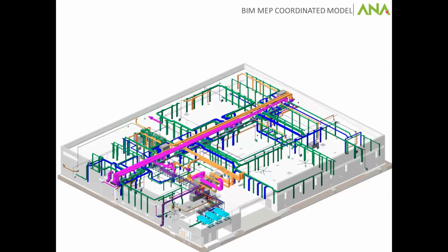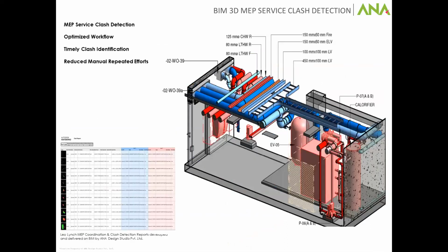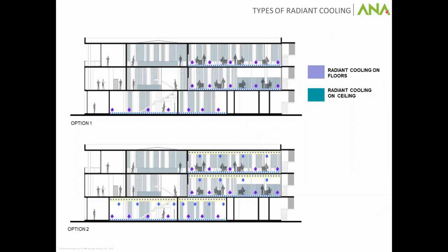inside the floor. And the return water which is coming back to the chiller in the primary circuit is passed through a plate heat exchanger, and the plate heat exchanger then sends out water at about 14-15 degrees Celsius. By the time it reaches the floor, it's about 17 to 18 degrees Celsius, and it creates a cool envelope which is about 2 meters higher than the floor.